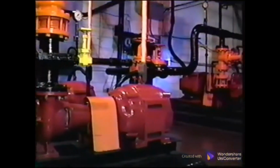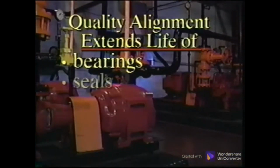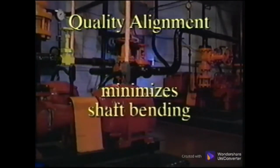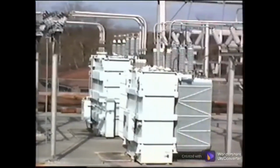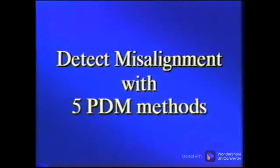In contrast, a machine in good alignment condition extends the life of the bearings, mechanical seals, the couplings, wear rings, and the shafts, as well as reducing vibration and minimizing shaft bending and cyclic fatigue. Quality alignment is proactive and removes the root cause of failures due to the forces of misalignment. In fact, studies have shown that machines properly aligned can reduce electrical power consumption by at least 4 to 9%.